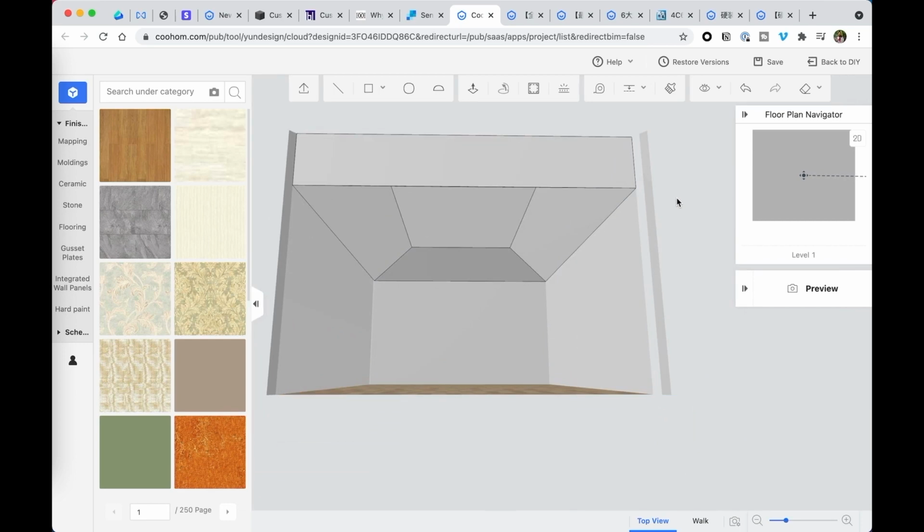Some of you might ask, what if I want to create a slightly more sophisticated tapered edge, you know, have a bit more advanced profile? How do I do that? Very easy and also super interesting way to do it. One of my favorite to try those two. This is called lofting. It's similar to follow the paths in SketchUp. It's basically once you have a profile ready, you can ask the profile to follow enclosed lines or surfaces. Let me show you.